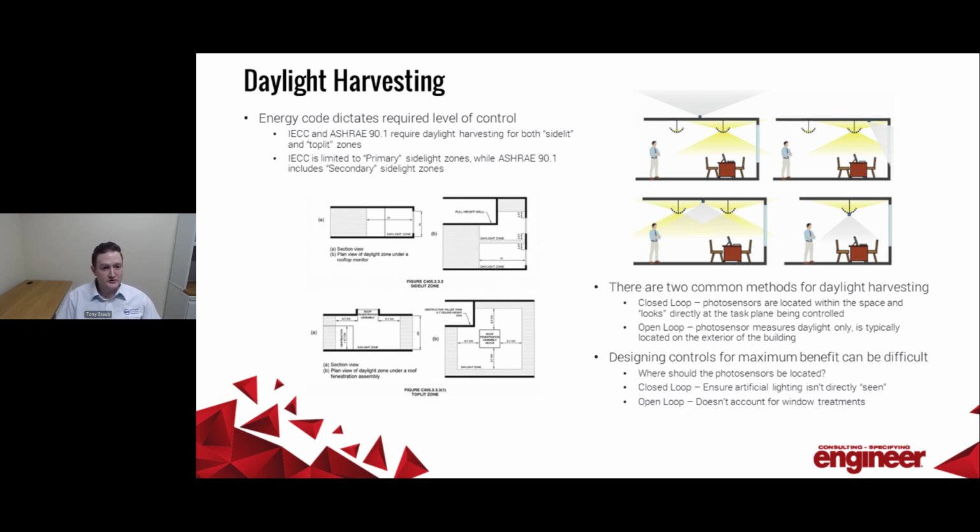So as to how we do that, really there's two common methods used in the industry today, and that is open loop and closed loop, which is essentially just saying, do the photosensors that we're using, are they looking at the space? Are they looking at the desk that I'm sitting at, judging the light there and adjusting accordingly? Or are they looking at outside? And whether that's looking at a window, or if the photocell's actually located outside of your building even, and picking up just daylight. Both can be effective in different circumstances.